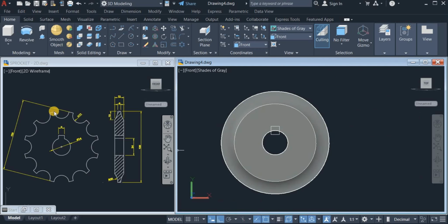Now again, how to create this curve, and I've used the circle command to do that. And you can see that the radius of this circle is 10. So come over again to the draw panel and click on the circle command. This time choose center radius. Then come to the quadrant point of this edge and draw a circle of 10 radius.